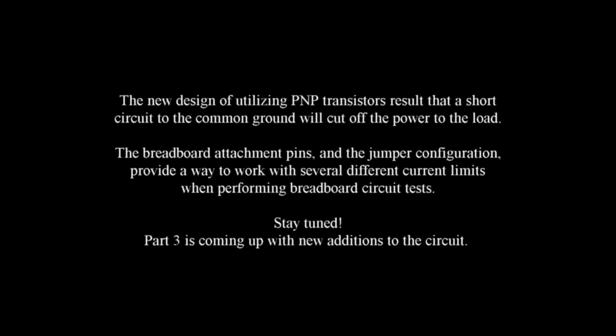Conclusion. The new design utilizing PNP transistors means that a short circuit to the common ground will cut off the power to the load. The breadboard attachment pins and the jumper configuration for RB provide a way to work with several different current limits when performing breadboard circuit tests. Stay tuned. Part 3 is coming up with new additions to the circuit.